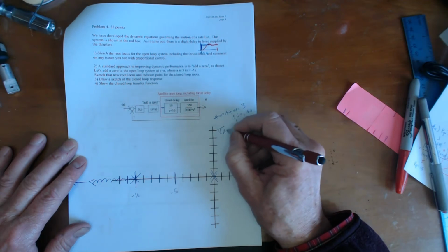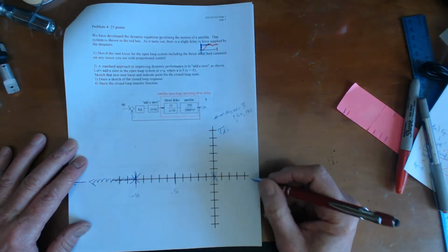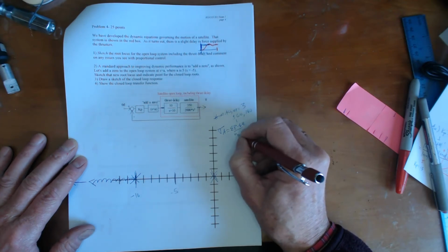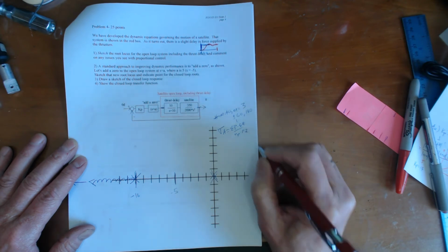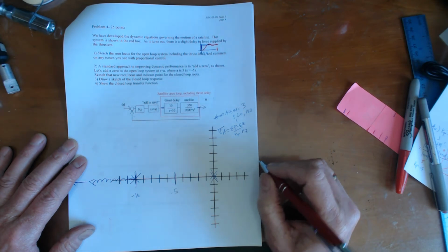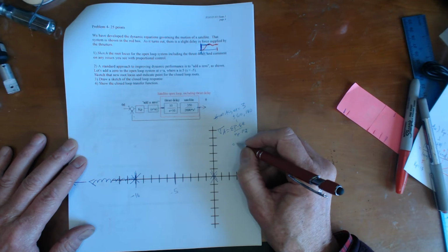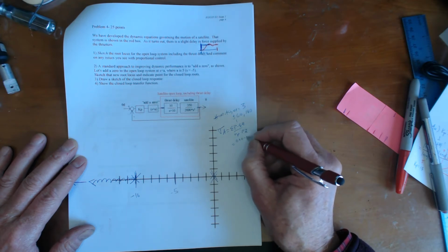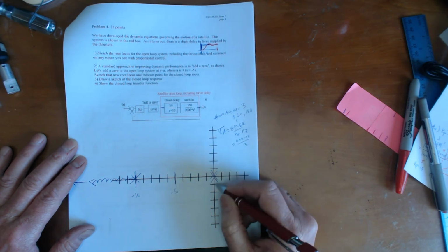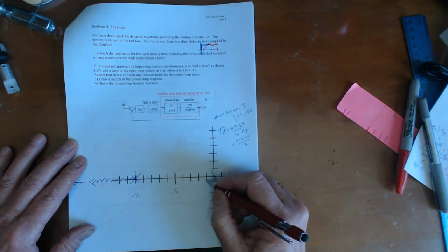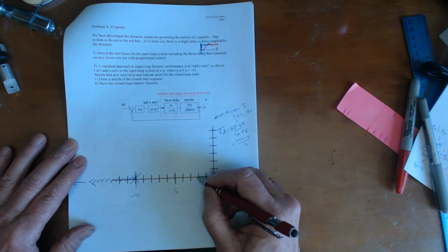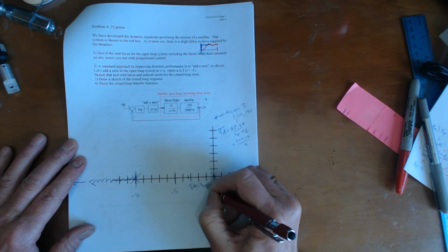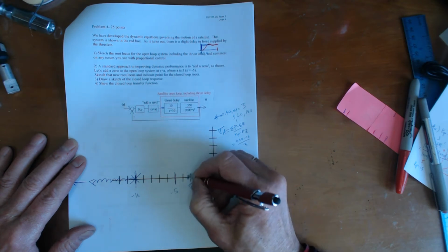I want to find the asymptote intercept point. It's the sum of the poles minus the sum of the zeros over the number of poles minus the number of zeros. That's going to be 0 plus 0 minus 10, over 3, or 10 thirds, which is 3 and 1/3. Here's sigma A equals 3.3, and so here's where sigma A is.